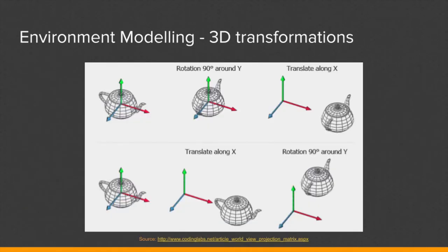To place the components in the environment, we use 3D transformations to translate and rotate the mesh models to the position they occupy in reality. For the robot links, this is done with the forward kinematics of the robot. For the objects in the environment, this is done by the transformations provided to the pipeline by the user.